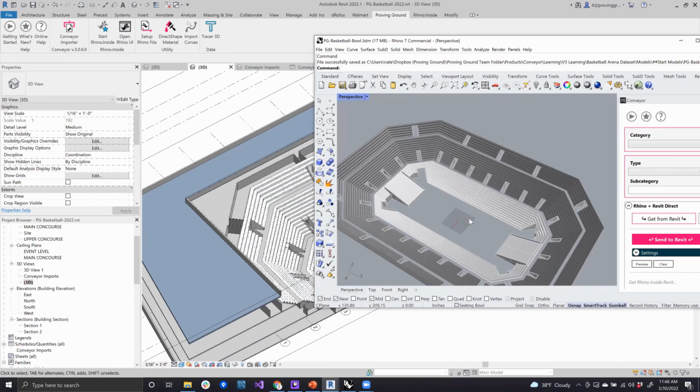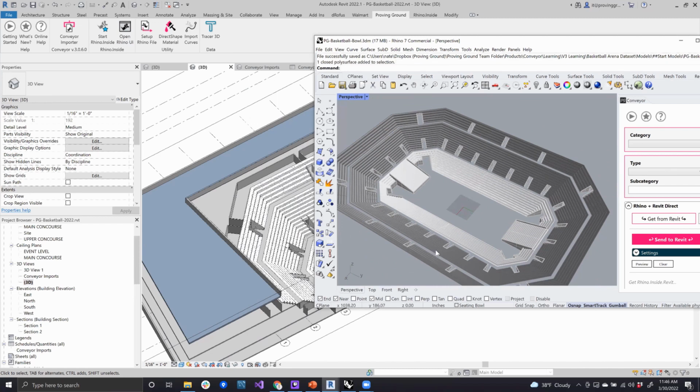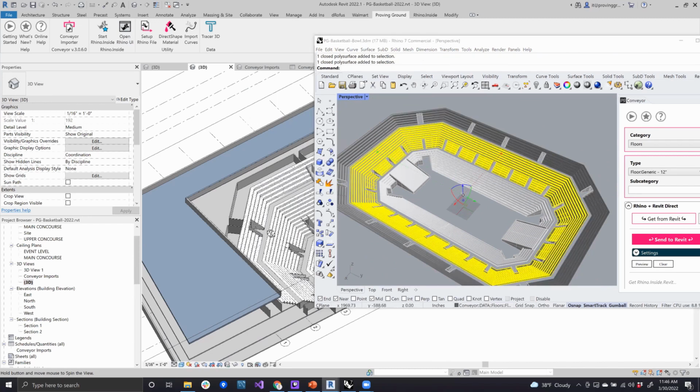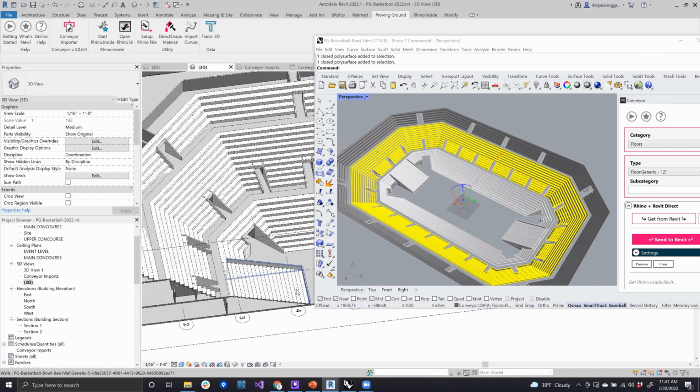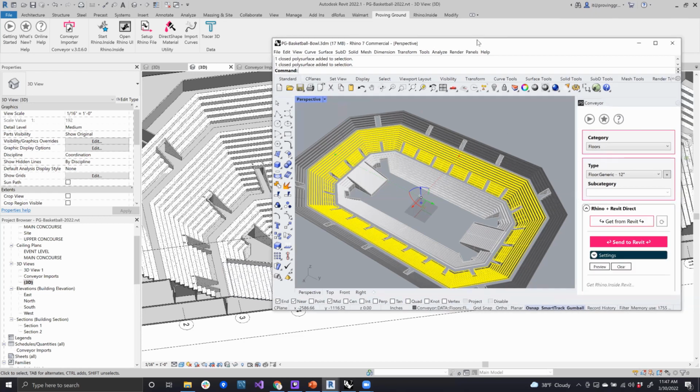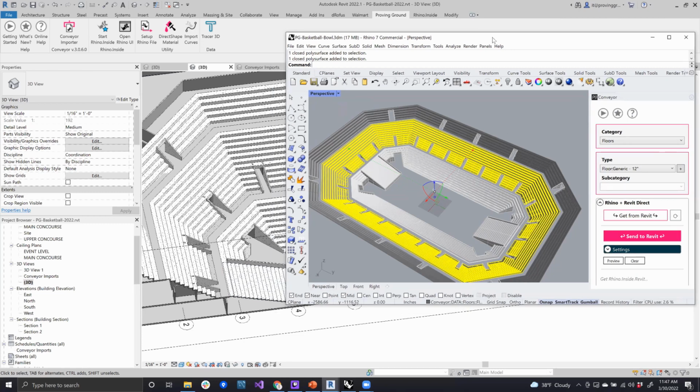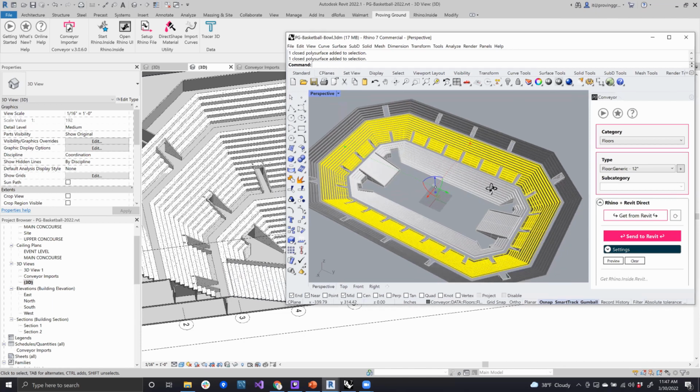And the idea so far is that we've been able to bring over geometry for the bowl, and we're using a direct shape method to accomplish this. Nicole covered different ways with which component families, more componentized architectural elements like seats, may be brought over. I'm going to jump into how one brings stuff back over into Rhino, and you might need things for reference because model coordination is extremely important in this context, right? You want to ensure that your models are aligned and located properly, and that you're using an appropriate amount of reference geometry to develop Rhino models.